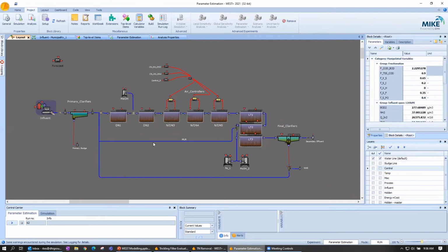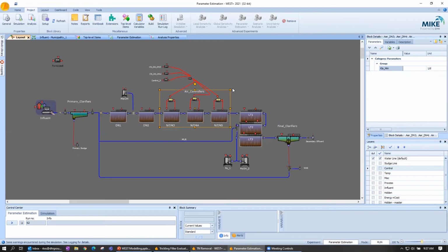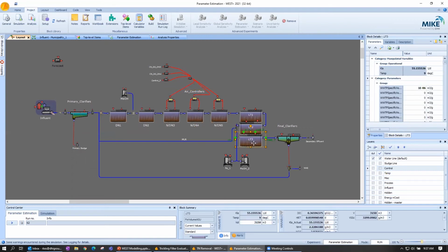This project decided in the design and planning phase, kind of like what we're just doing for the American project, but the engineering team decided that these 3 denitrification tanks would actually be swing zones, and the final project ended up making aeration tank 3 also a swing zone.